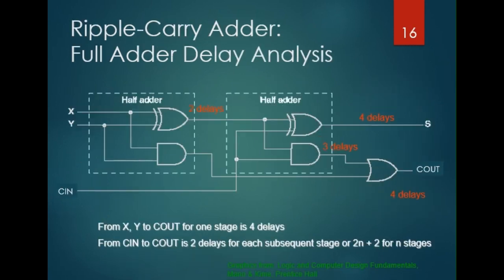Okay, so this is the ripple carry adder that is composed using 2 half adders. Just now, I briefly mentioned that one of the limitations of using a multiple-bit ripple carry adder is that there is a long propagation path that involves the carry signals from one adder to the next adder. So how does this propagation path happen and affect the performance of the multiple-bit ripple carry adder? Let's look at the delay analysis.